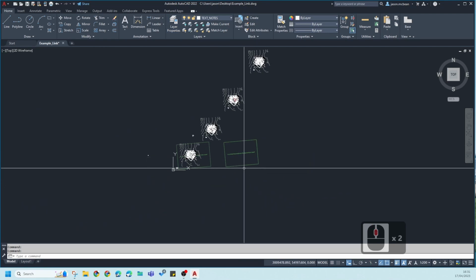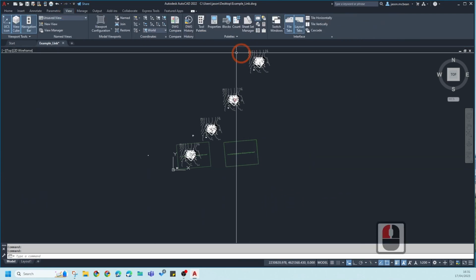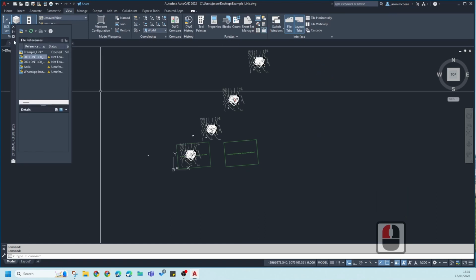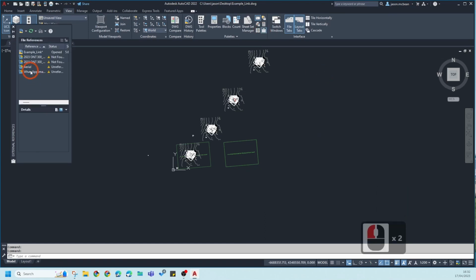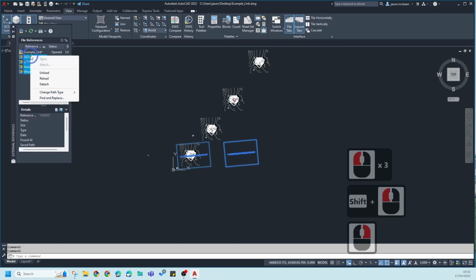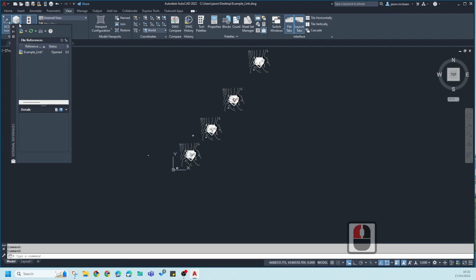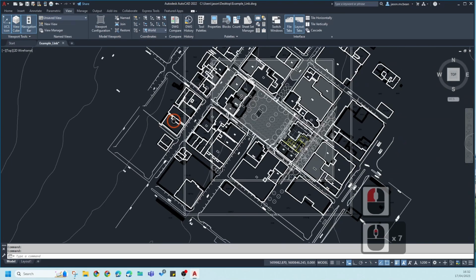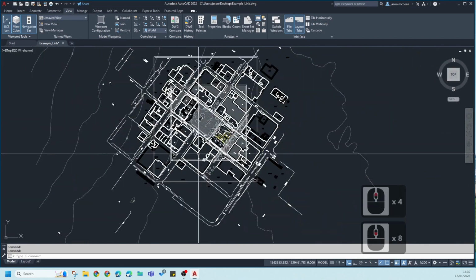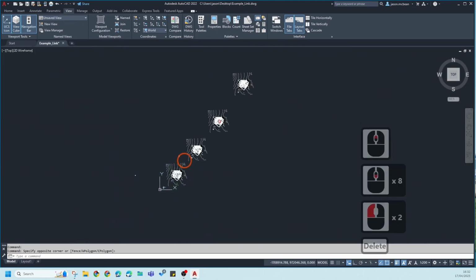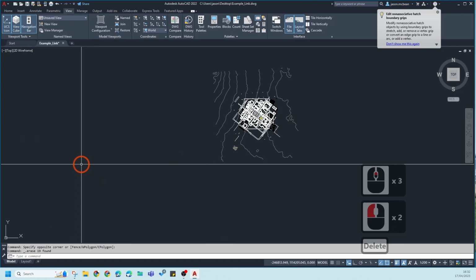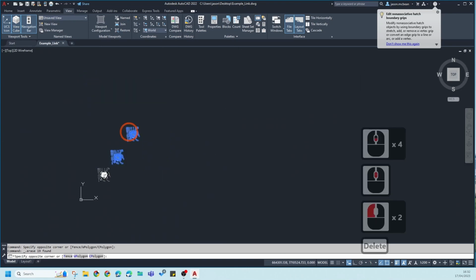So you'll need to go to the external reference command. You can use View and go to External References. You can see there's lots of external references, so let's just get rid of all of those. Detach, fantastic. Now I'm going to work just with this view over here, so I'm going to delete everything else in this drawing and clear out all the unnecessary information.